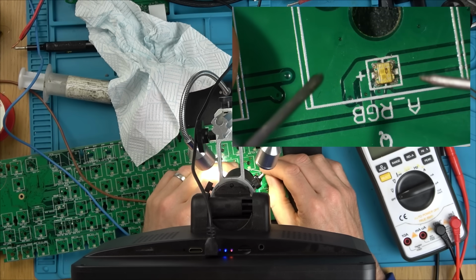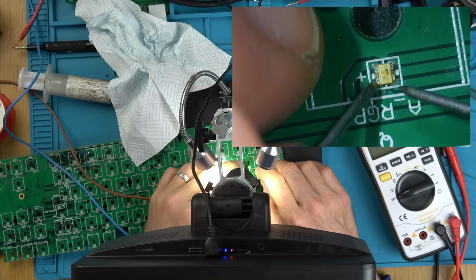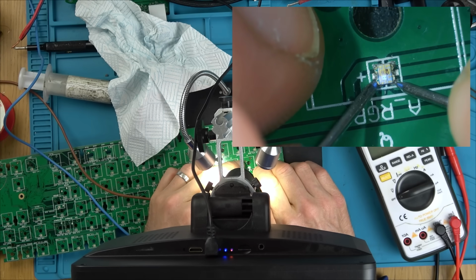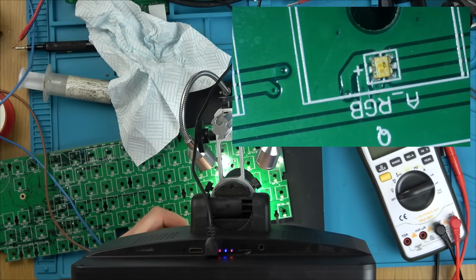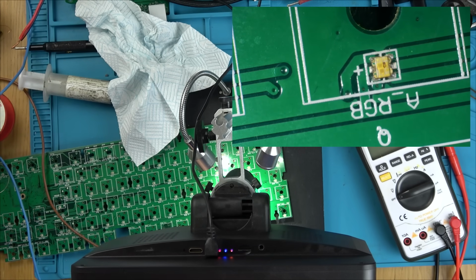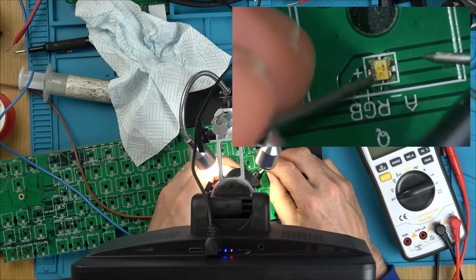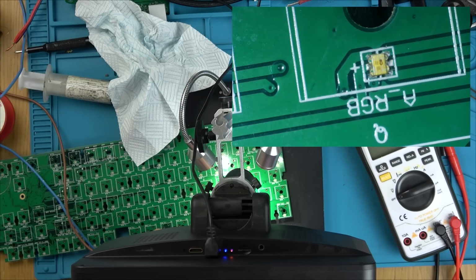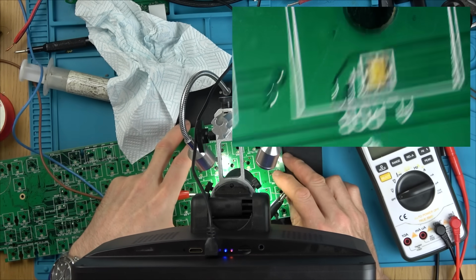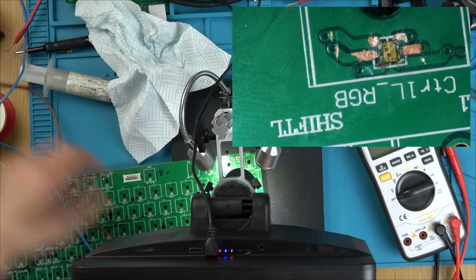So basically I've got my bench power supply set to 2.4 volts. And if you have a look, if I go across these top two, you can see it's lighting up blue. If I go across the bottom two, it's lighting up green. Now I need to lower this one down because the red lights up on next to nothing. So I'm going to go all the way down to 1.7 volts. And if I go on the middle two, you can see that the red is lighting up. So yeah, so we now know 100% that this one down here isn't doing what it needs to do, because if I go back up to